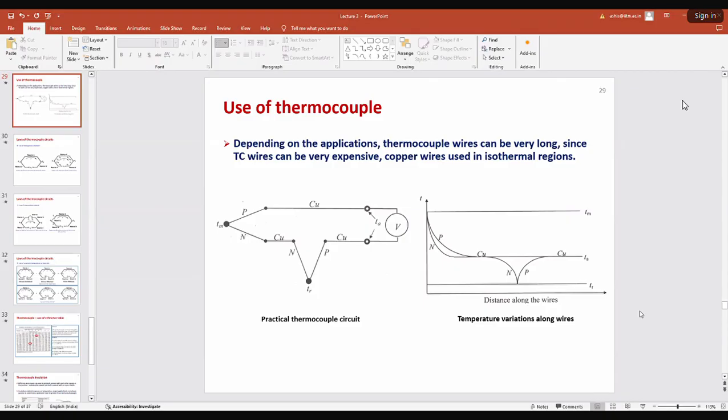What I'm saying is that between two different methods, my experience has been that if it is within plus or minus 1 degree, I can tolerate it, depending on the way the IR is calibrated and the way the thermocouple is calibrated. Less than 1 degree one can tolerate. But if it is a few degrees, 2 degrees, then there must be something wrong. In this particular case, I really do not know what has gone wrong.